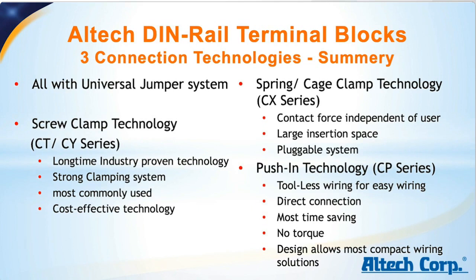Now, push-in technology is the newest of all three technologies. There's no tool needed, and connections are just made by connecting a wire directly to the terminal. As far as installation goes, the CP series provides the most time savings, which is very significant, obviously, if we have a system with many IOs. Also, push-in technology should be the choice for low voltage systems when we have small wires. Here, it is the most compact, and besides time savings during install, here it also provides the most space savings as well.